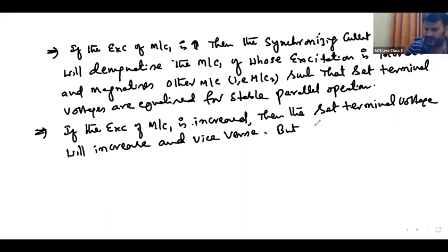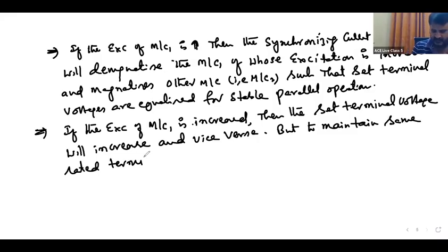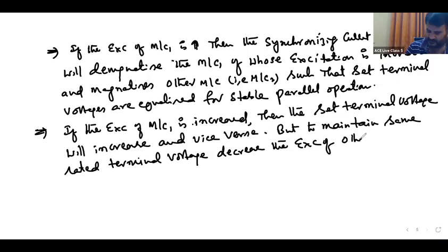But to maintain the same rated terminal voltage, decrease the excitation of the other machine. Decrease the excitation of the other machine.